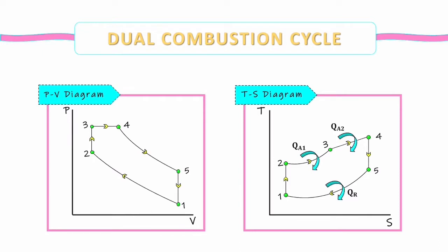The exhaust valve opens at point 5. The exhaust stroke is directly after this decompression. As the piston moves from bottom dead center or point 1 to top dead center or point 0 with the exhaust valve opened, the gaseous mixture is vented to the atmosphere and the process starts anew.